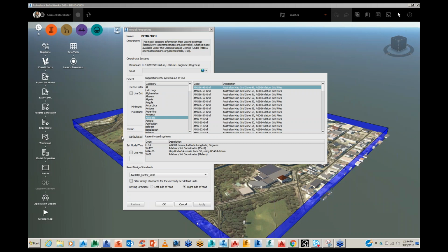So the best way to do it would be to move it away from 0,0 to the correct project base point with the northings and eastings. Some people don't like to do that. The option I probably recommend here would be to use the internet mapping system to get it close within a few meters. That would probably be the better way to do it.